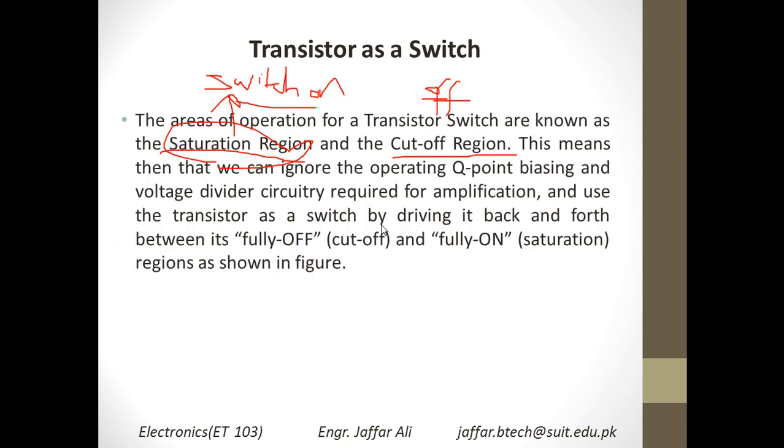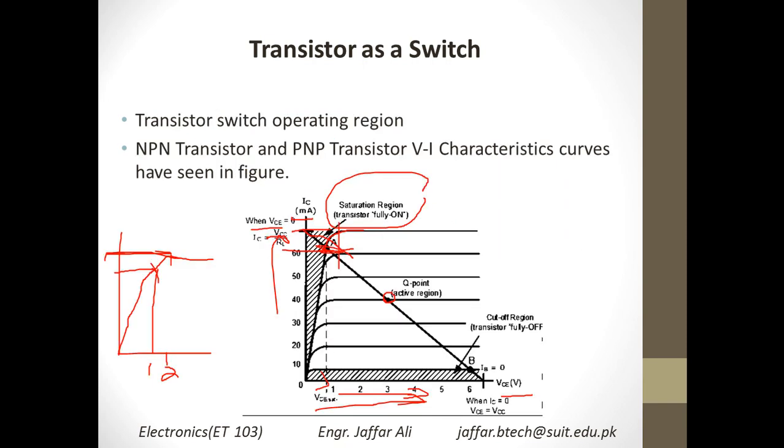Similarly, if you are below the amplification region, at this point, with very low voltage, less than 0.7 volts applied in the VBE, your device will be turned off because the 0.7 will be dropped by the diode itself, that PN junction by itself. So I prefer you to apply low voltage at the input when you want your transistor to be in switch off mode.